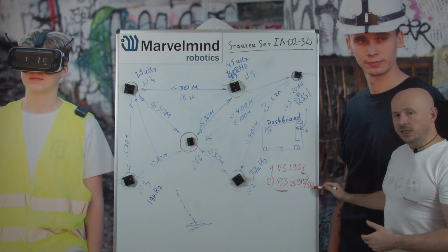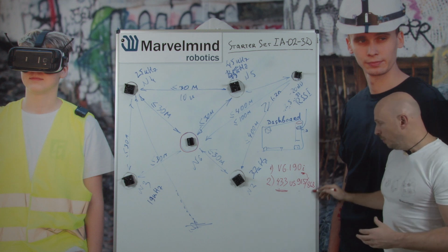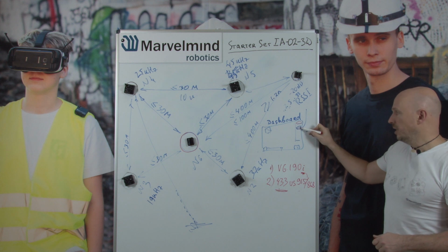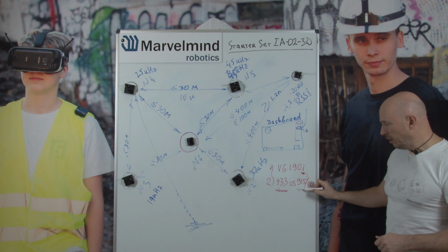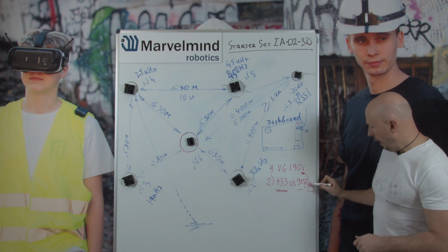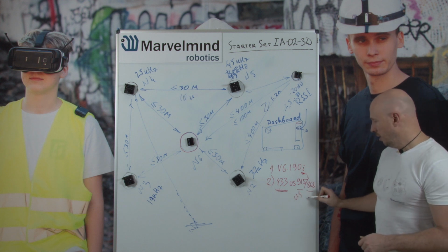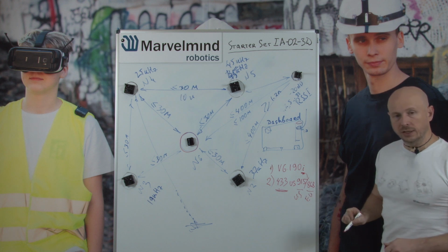Let's talk about 915 a bit more. The 915 band and the 868 MHz band are close to each other. So for these bands, you can choose software-wise settings inside the dashboard and set them either to 915 frequency or 868 frequency. 915 is the US band and 868 is the European band.